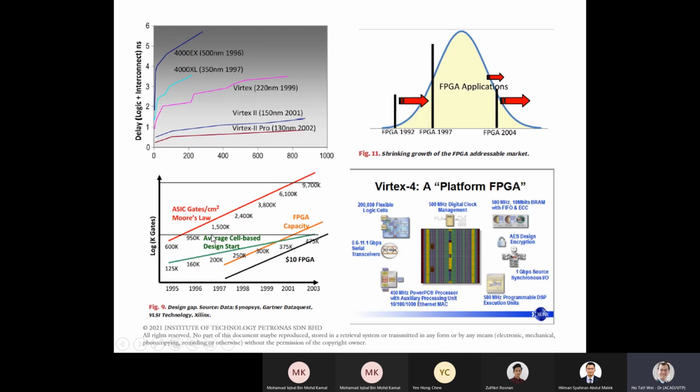1.5 million logic gates is roughly around this line. So right now our capacity is designs that have roughly 2 million logic gates. You can actually implement them completely with FPGA. And what's actually very interesting is that a $10 FPGA can now implement something roughly like a design with maybe half a million or close to 1 million logic gates.